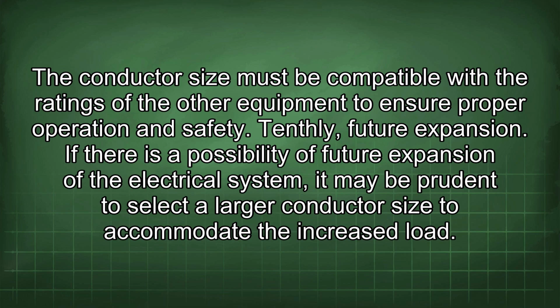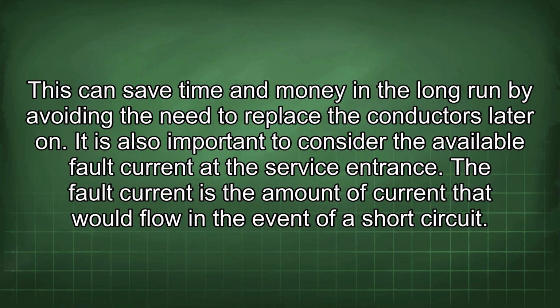If there is a possibility of future expansion of the electrical system, it may be prudent to select a larger conductor size to accommodate the increased load. This can save time and money in the long run by avoiding the need to replace the conductors later on.